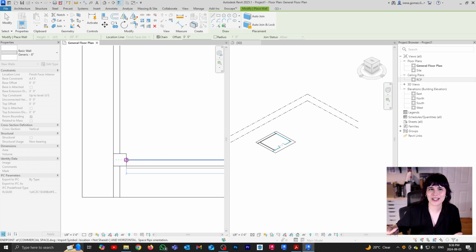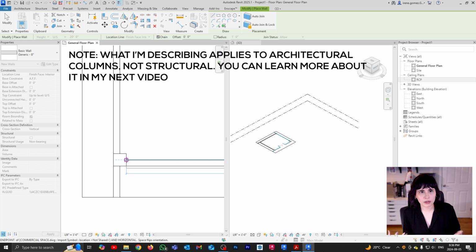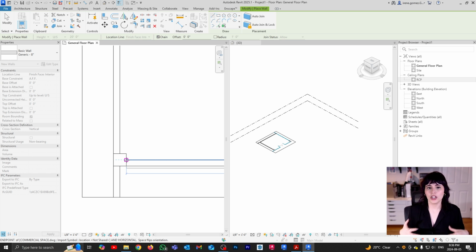you can ignore everything. You're just going to go crazy and draw those walls to fully enclose your space. Because what's going to happen is that depending on what geometry you're creating, it actually responds to the other things that exist. So in the case of columns, columns usually become integrated. They merge with your walls. So when you're drawing your walls, you can just go ahead and ignore your columns. I know some people are super finicky about it and they want to stop it. You don't have to if you don't want to.